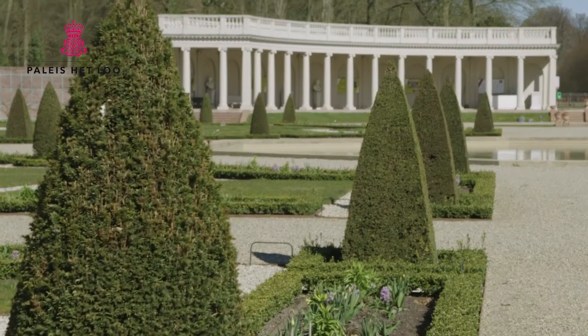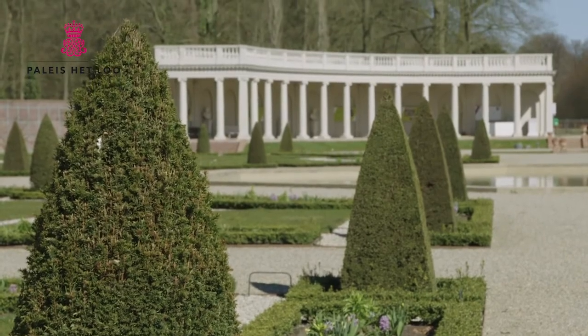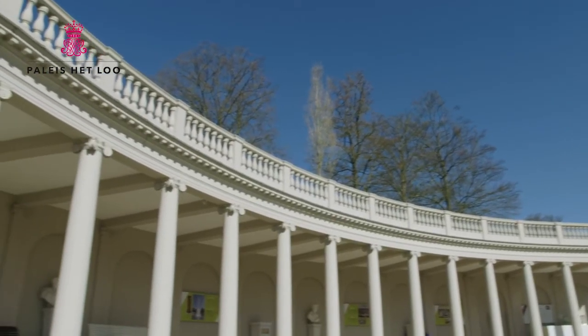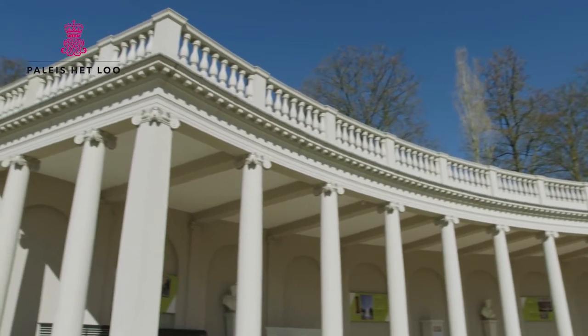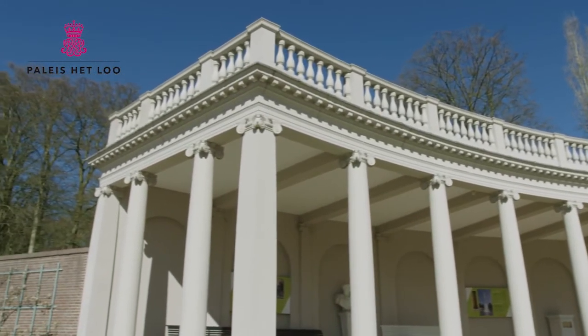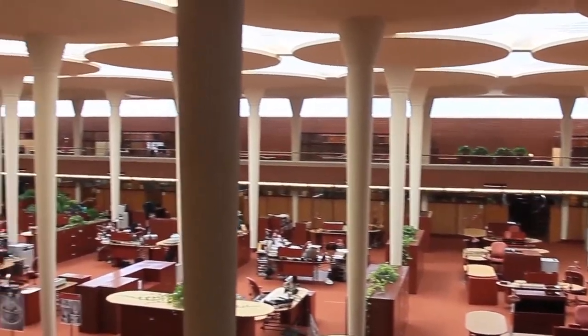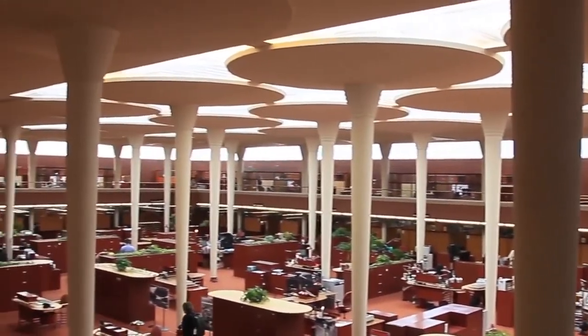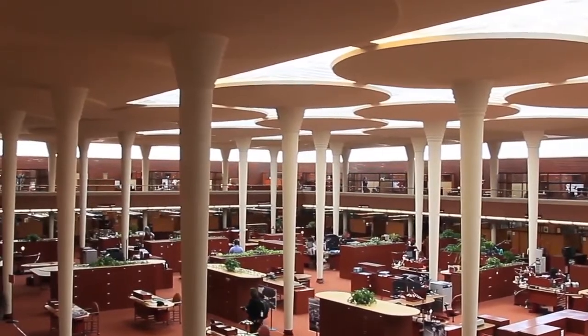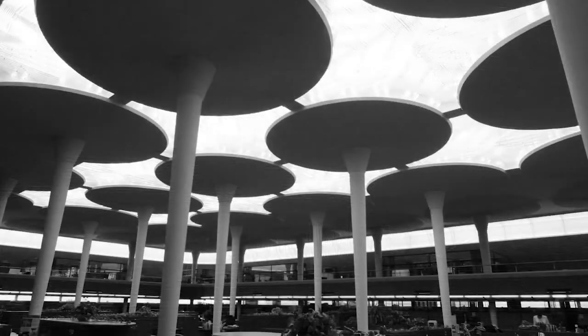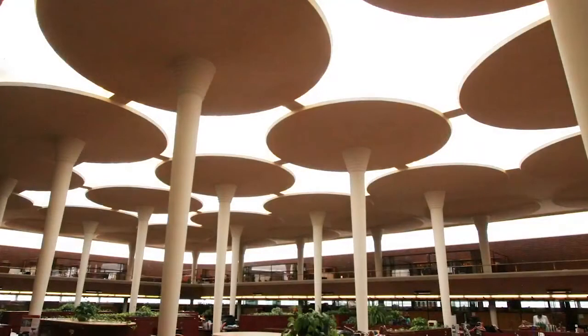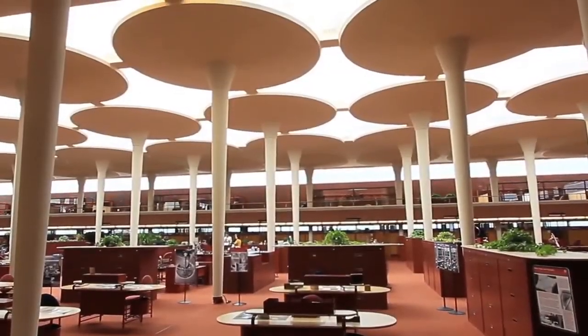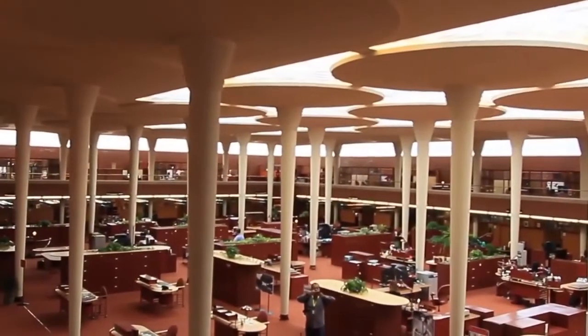A row of columns can also engage a wall and become a pilastrade that supports the wall, articulates its surface, and tempers its scale and rhythm. A grid of columns within a large room or hall not only serves to support the floor or roof plane above, but the orderly rows of columns also punctuate the spatial volume, mark off modular zones within the spatial field, and establish a measurable rhythm and scale that makes the spatial dimensions comprehensible.